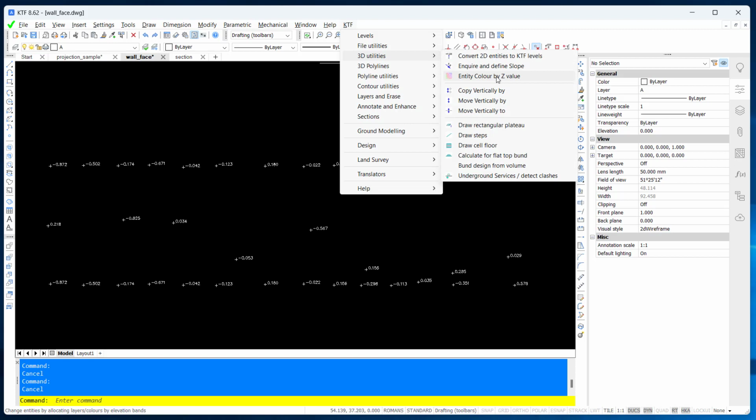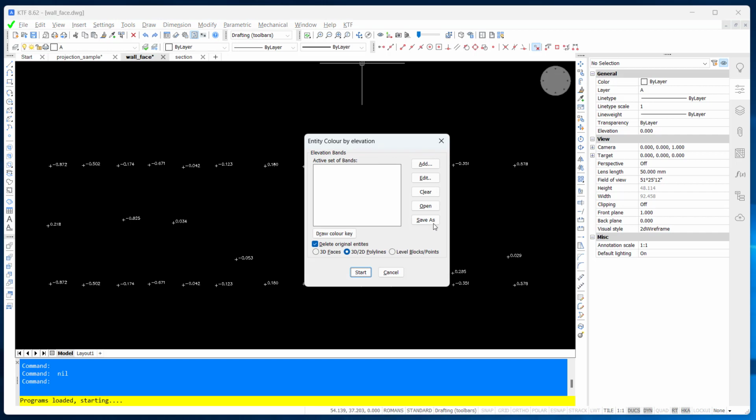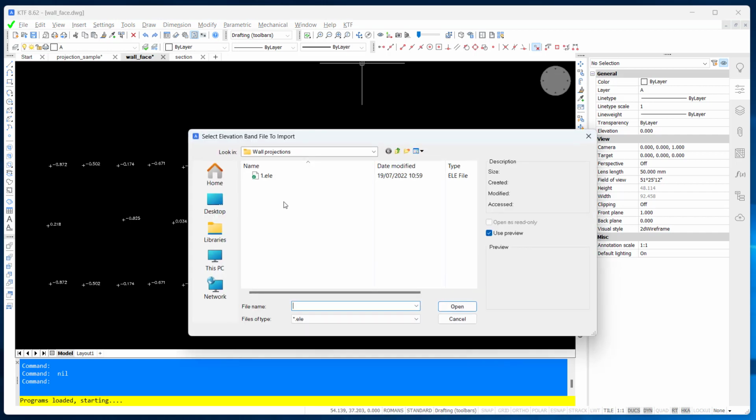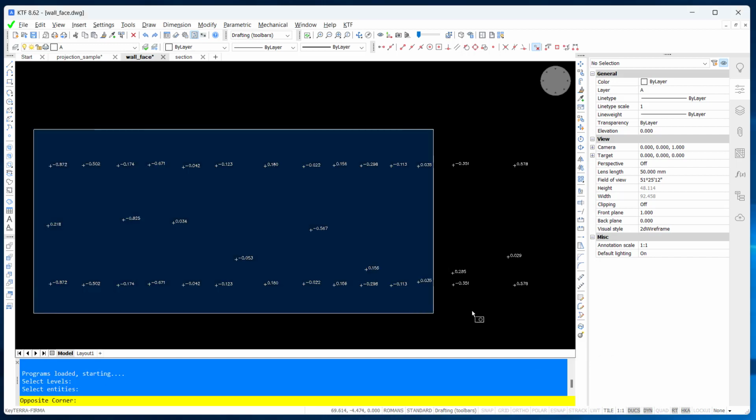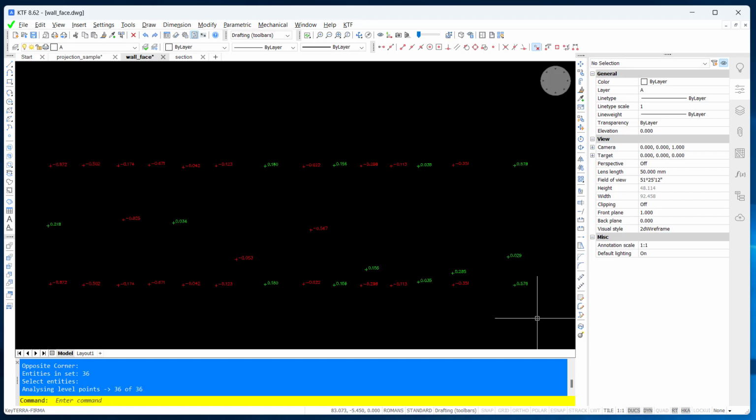Remember, negative values in this drawing mean they are left hand side of the center line, positive they are right hand side. So here I generated quickly already elevation where it's on different layers and colors there. So just go for it. So window, select these ones, and then you see which ones are on which side. So handy little thing. Now to sections.